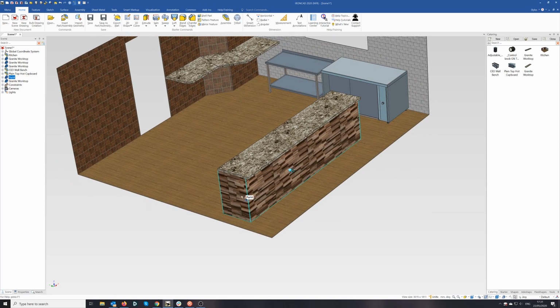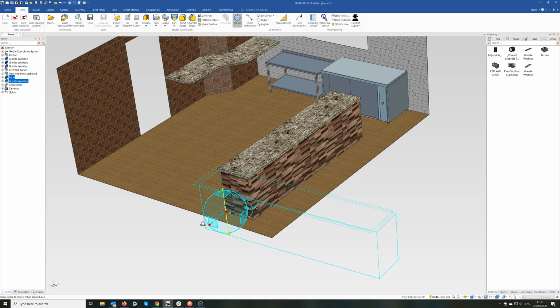I can actually move that forward. I want to move that forward. I said 60 mil, so we've got a bit of an overlap on here. So let me just move that forward 60. There we go. And let's select this one, put the tri-ball on, put it down to this corner here, relock the tri-ball, and rotate this round. And we're going to create a copy here. I'm going to make that 90 degrees,